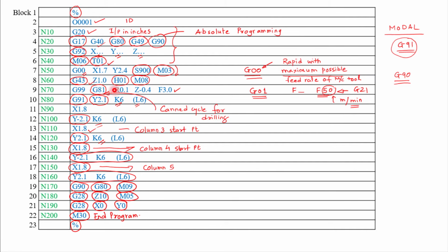When the tool is traveling from the safe position to the reference position above the work part, we are asking the controller to activate G43, tool length compensation along the positive direction. We are assuming that the part 0 setting has been done by using a tool shorter than tool number T01, or by the shortest tool among the tools available in the magazine.